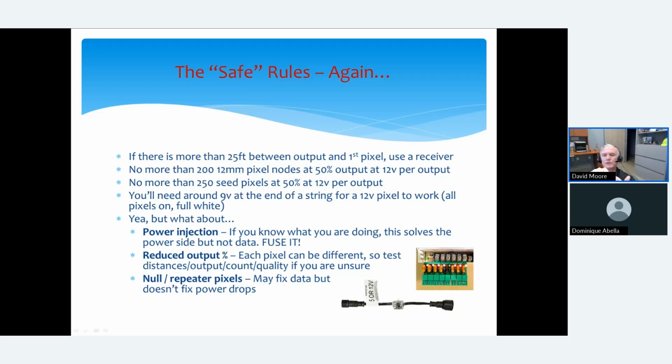If you put a multimeter in there and you measure something below 12 volts with the lights on at full white, and it's below 9 volts, you're going to get some weird stuff. The chips just don't operate. I know they run at 6 volts, or 5 volts. Why 9 volts? Because there are some dropping pieces in there, and some chips will work better at that. Some chips will work okay at that. Some will go bonkers at 9 volts or below. So it all just varies.